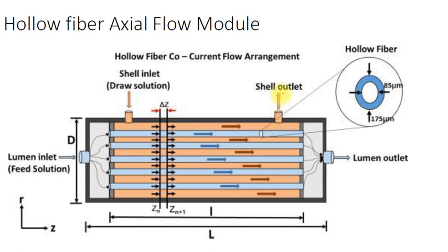Okay, so this type of shell and tube, hollow fiber axial membrane is generally used in ultrafiltration setups, and it is quite useful because the membrane density is quite high, but this type of setup only uses hollow fiber membranes.